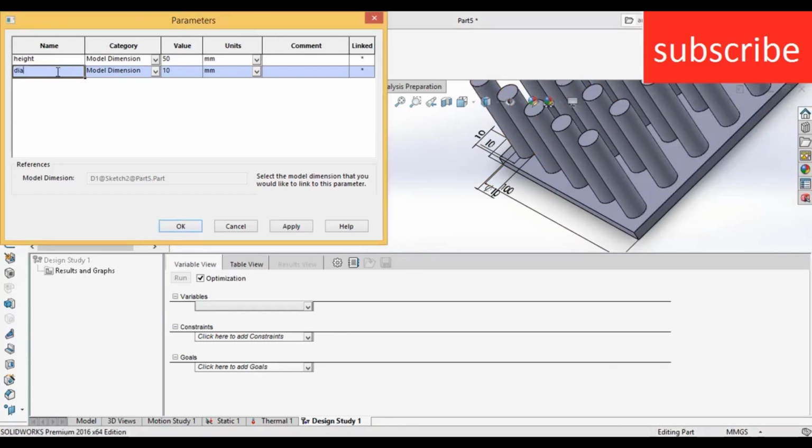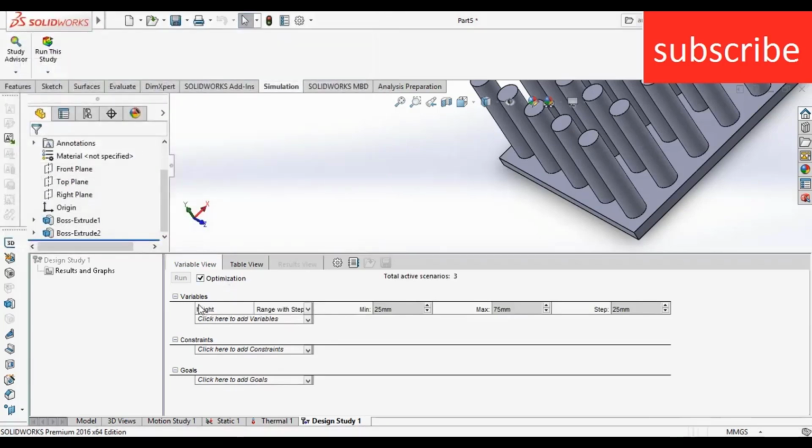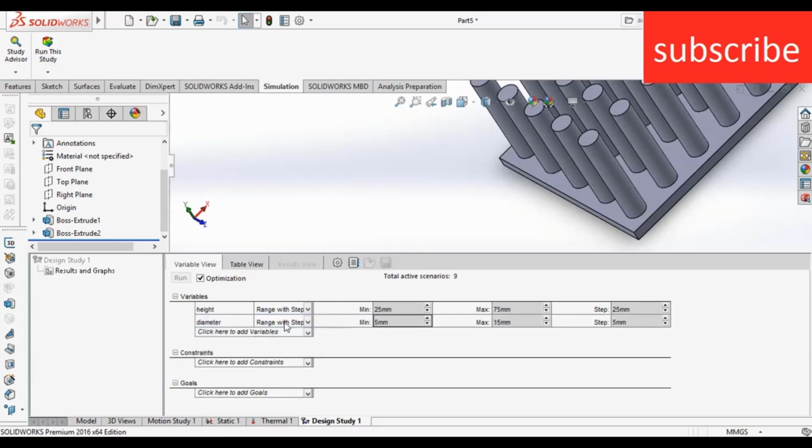Type diameter. Now here I am going to change only these two parameters to get maximum heat transfer. So click apply. After that click OK. Now in variables you will only see height, not diameter. So click down this and select diameter.